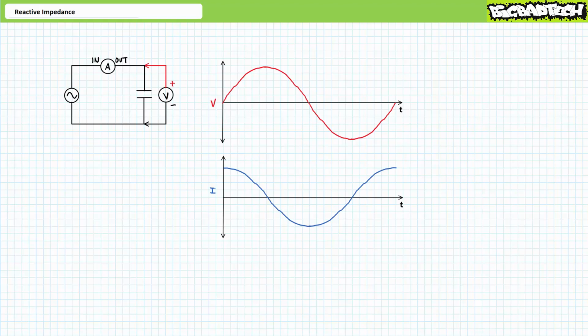During the charge phase, current rushes into the capacitor and capacitor voltage rises. During a subsequent discharge phase, current rushes out of the capacitor and capacitor voltage drops. The problem in identifying the present state of a capacitor in AC systems is that the polarity in AC systems cyclically oscillates at a frequency too fast to allow a technician to change the leads of a voltmeter or ammeter to adequately reflect the actual state and polarity of the capacitor.